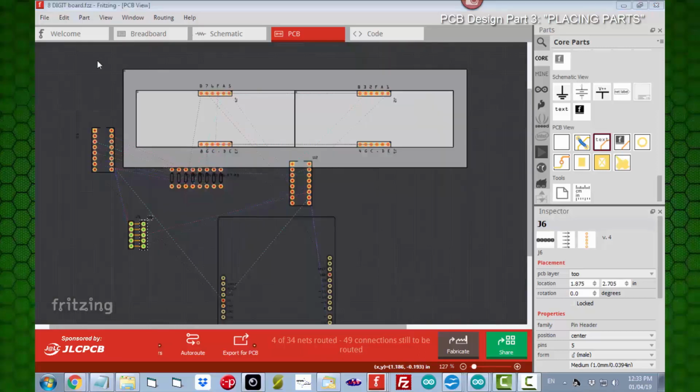Now, a real important thing about doing a project like this in Fritzing or in any program where you're moving a lot of objects around and changing things is to save your project often. And I don't mean just save it again and again and again with the same file name. What you want to do is save it in increments. So if we completely botch something up, it's easy to get back 1 step or 2 steps along the way.